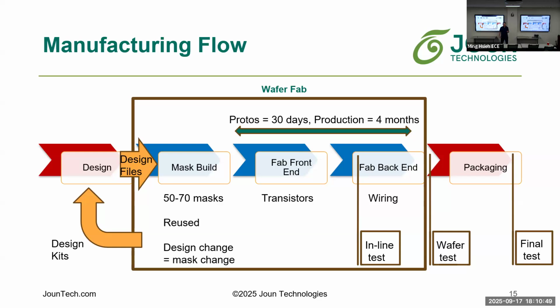So this is why they have to consider backups and all sorts of things. It also tells you why it's so important to control everything associated with manufacturing, right? So to ensure that when you get here, you have a high probability that this works. When the chip is done, you do a test and you identify how many of them are good. On a typical process, you want this to be very high, 90% or better. And then it's cut up and packaged. They do another test, and that becomes the component that typically goes into an electronic system.